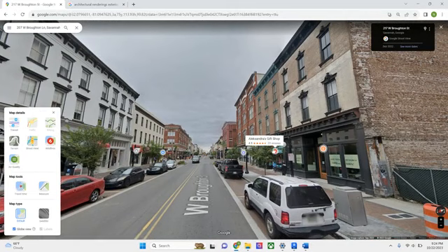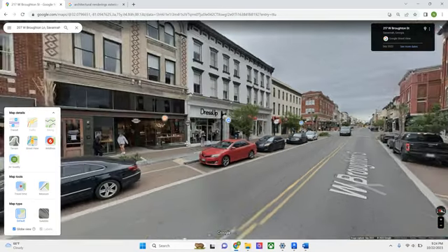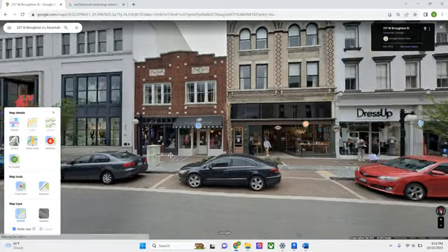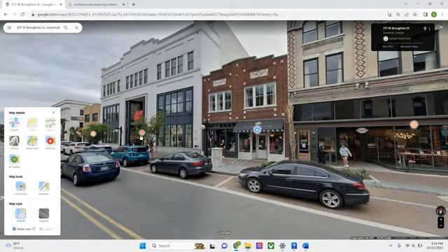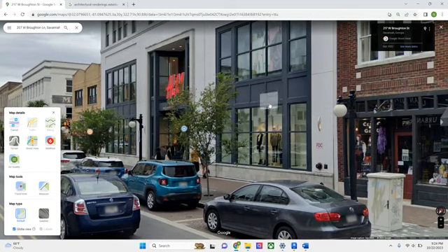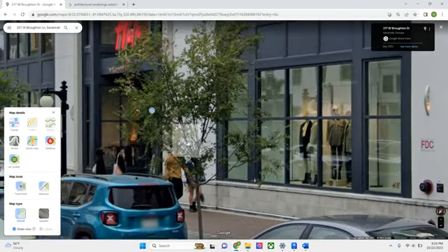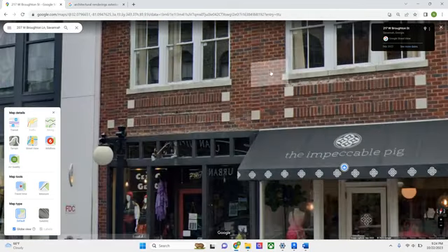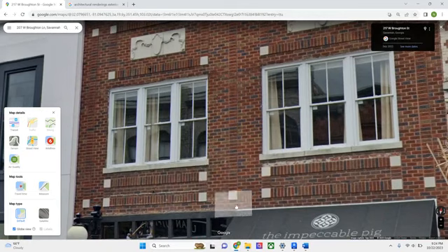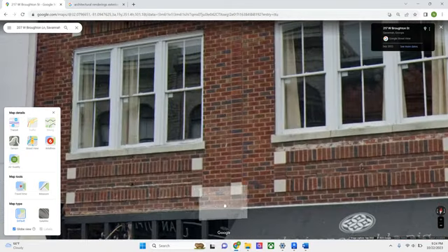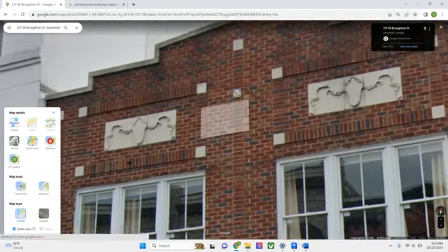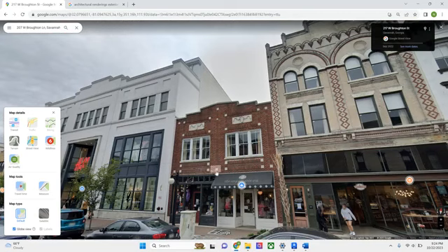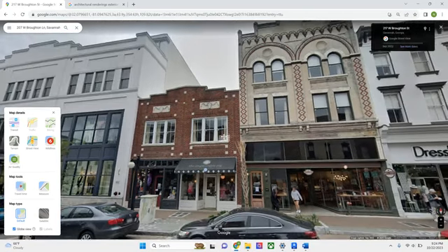So if this is 3 stories, I'm just probably going to assume a standard, even though it's not necessarily correct. I might just assume a height here, and you'll notice me do that because I will probably just take this person and scale them up. Sometimes I count bricks to see how tall something is. So I might start at this brick, so I'd be like 1, 2, 3, 4, 5, 6, 7, and go all the way up to the top. And then I can roughly get an idea of how tall that facade is.